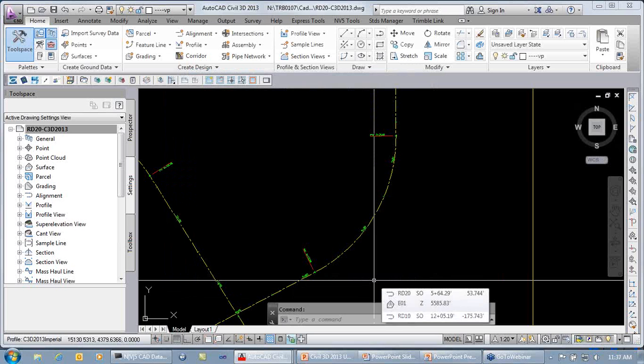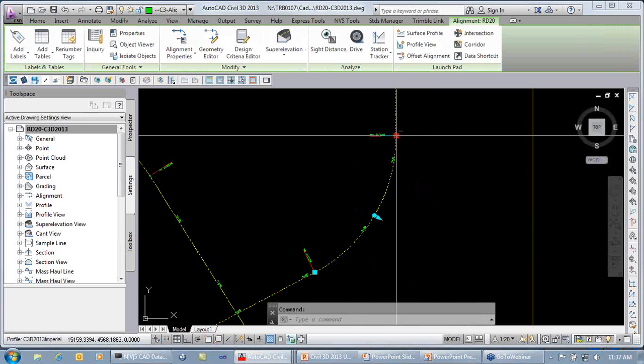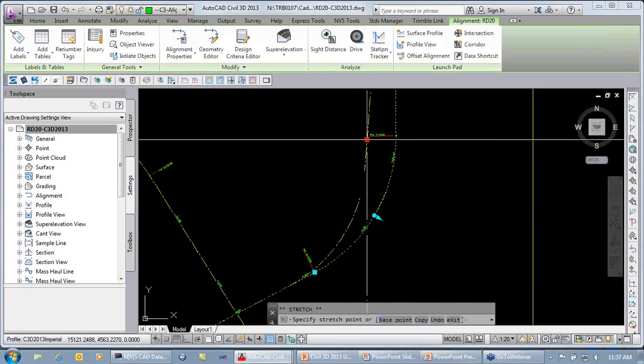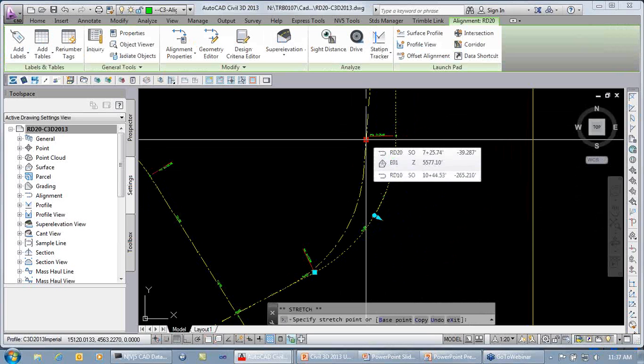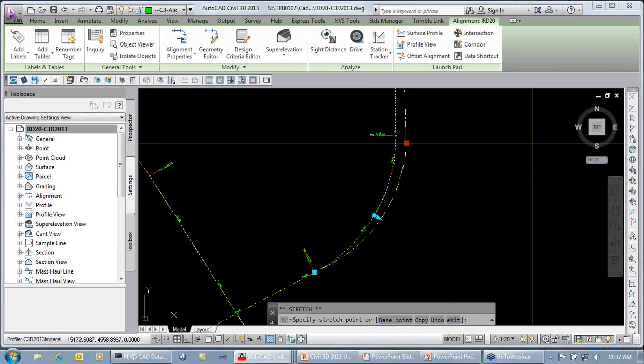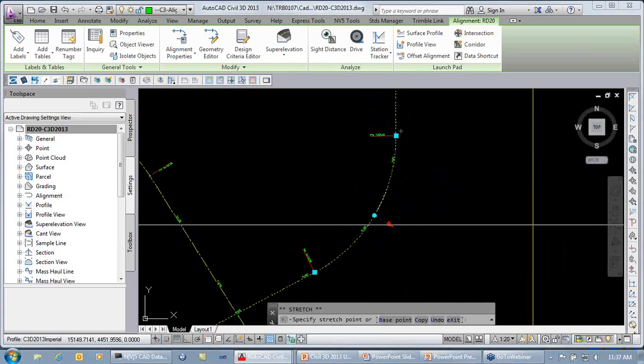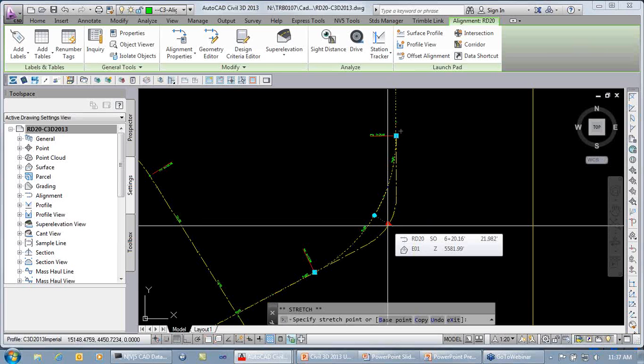And then we would add what are called floating curves. I have an example here of this alignment. If I change where my endpoint is located on my tangent, my curve will maintain tangency. When I change the endpoint of my line segment, my curve segment will stay tangent to that. As I move that around, you'll see that stays put. Same thing if I adjust the radius of my arc, you'll see that it does extend in the tangents, and the arc length will adjust, maintaining that tangency.